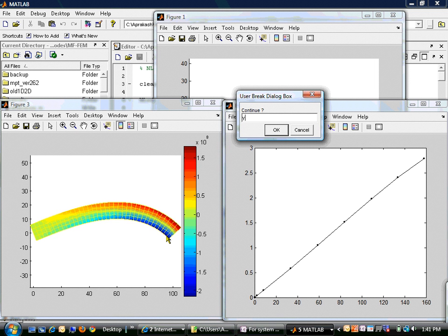So even for linear problems, when we are talking about eigenvalues of the element matrix, those eigenvalues which are 0 represent rigid body modes. So having a rigid body mode is also some sort of an instability. So let me continue this analysis.